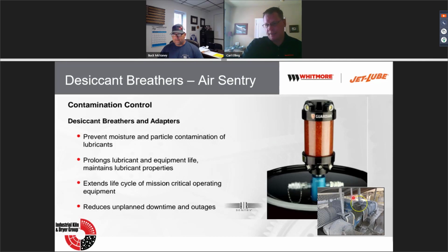But the majority, like I see pictured here, we still have vents. Just understand, using this vent, it's allowing all of the air to come into it and all the moisture to come into it. It kind of defeats the purpose. What is it protecting against? Probably getting rain directly into the gearbox is all it's really doing right now.